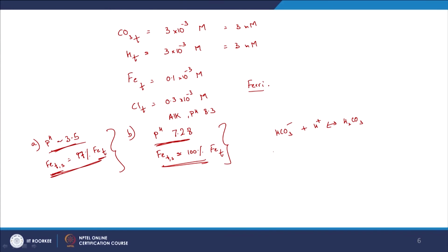Why is that? So here the key is to understand what we talked about earlier. How is this particular mechanism going to work? We know that there are two aspects, or three. There is charge neutralization, as in the colloids are negatively charged. So any positive charge that you add is going to neutralize the net charge on the colloids or suspended particles, allowing them to overcome their forces of repulsion.